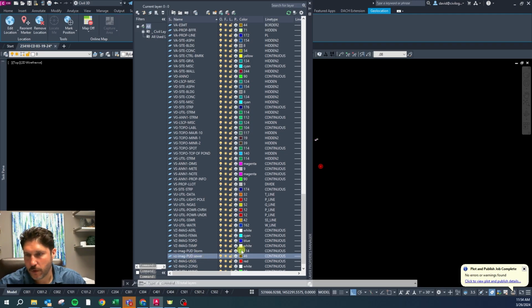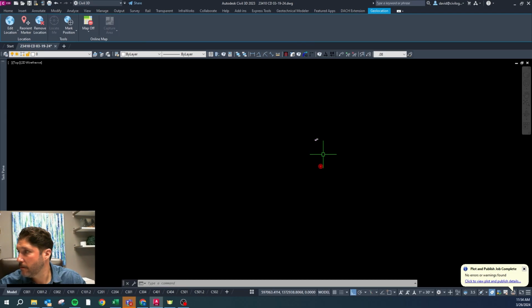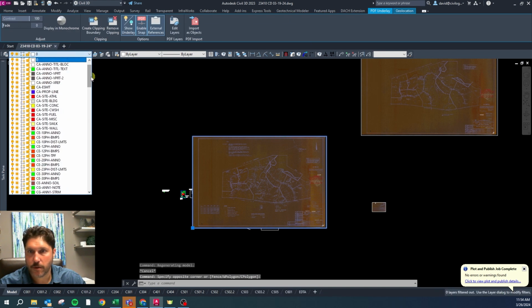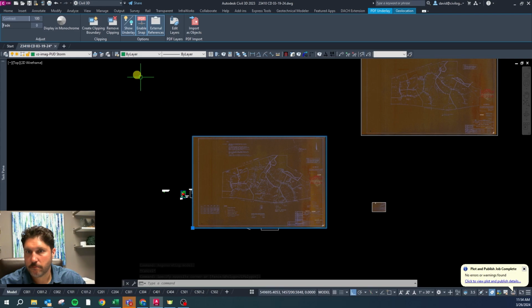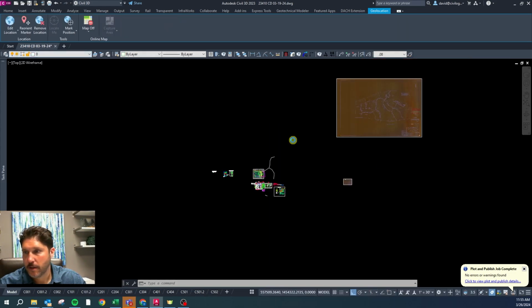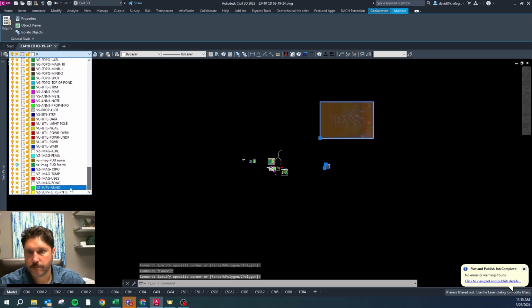And even the small image was also a sewer plan. So we'll put those two on the same layer. So this one we're going to put on the storm layer, and we have that one lined up, so we're going to turn that off now. And then these two we're going to put on that sewer layer.